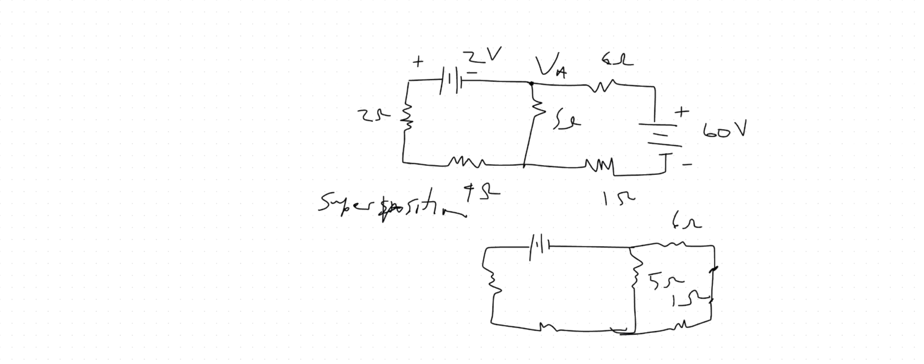Understand? So this here is a 2 ohms and this is a 4 ohms. No, you can work this circuit first. This is another method called superposition, which is what we're doing now. You work one source, short the other source. If it was a voltage source, if it was a current source, you open the other source, and you work the circuit till you get a voltage, which is what we're looking for, the voltage at this point.